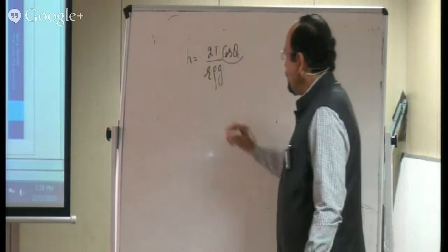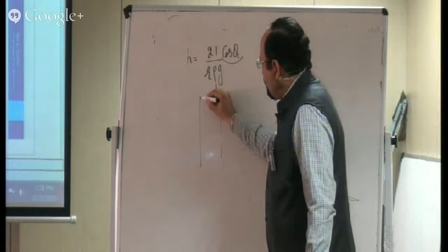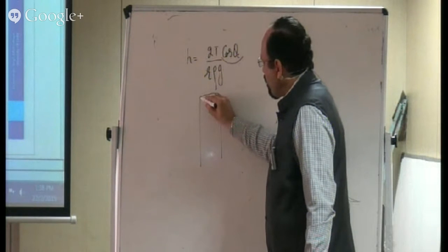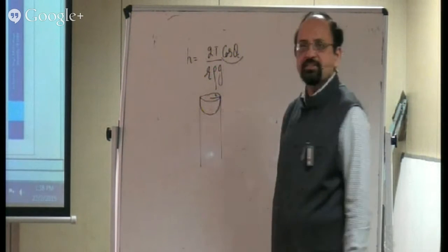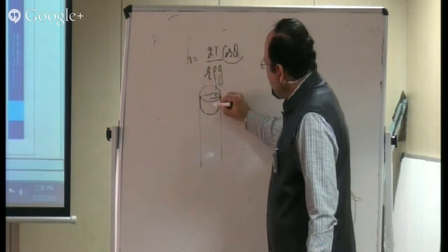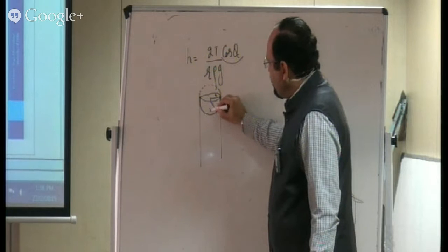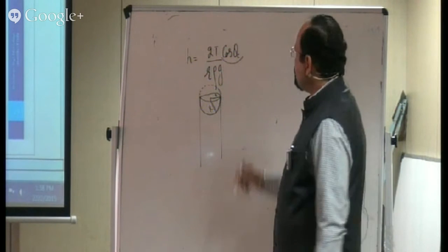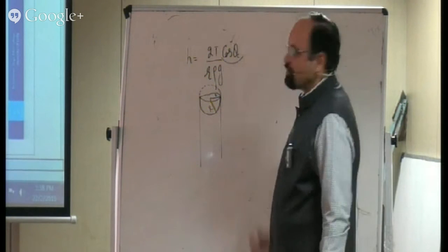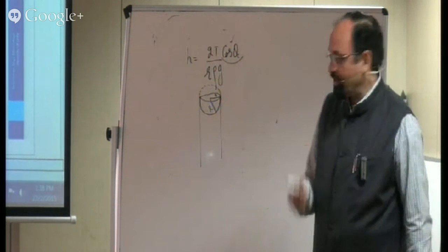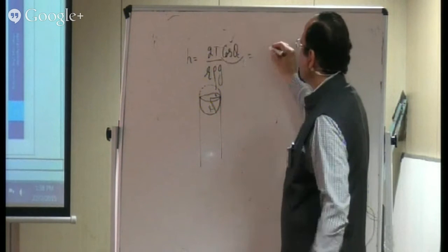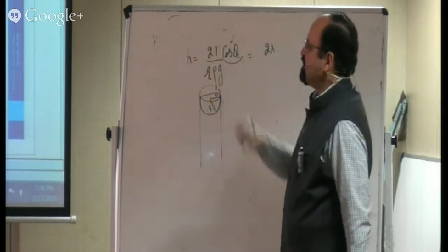There's a difference. Radius of capillary is this radius. But when we talk about the meniscus, meniscus means the surface. Its radius is different. I have to complete this sphere and then talk about the radius, that is the radius R. So this time we are taking the radius of the capillary, so I have to continue with this cos theta C factor there for correction. Rest is simple. Do you want to do it in SI system? Then the surface tension is given to you